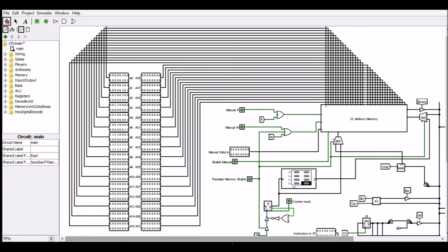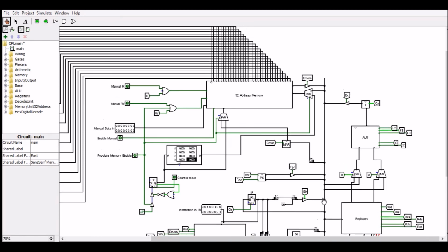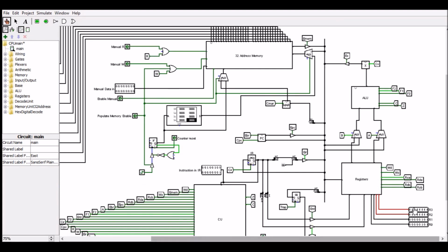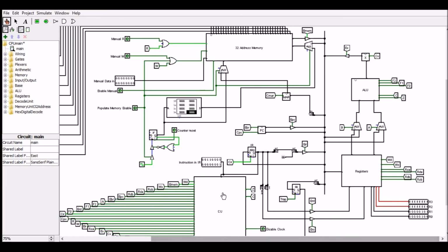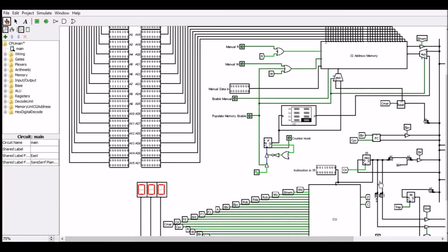And if we go back, we should see that it's clocked into the intermediate register X because we have something on the bus already, so it cannot go straight back into the register R0. So if we tick again, we should enable, oh yeah, so the value has been enabled onto the bus and has been written into R0 at the same time as the reset has happened here. So it was too quick to see, but it has happened. We can see that the result has happened. So onto the next address. I think we've already fetched it.